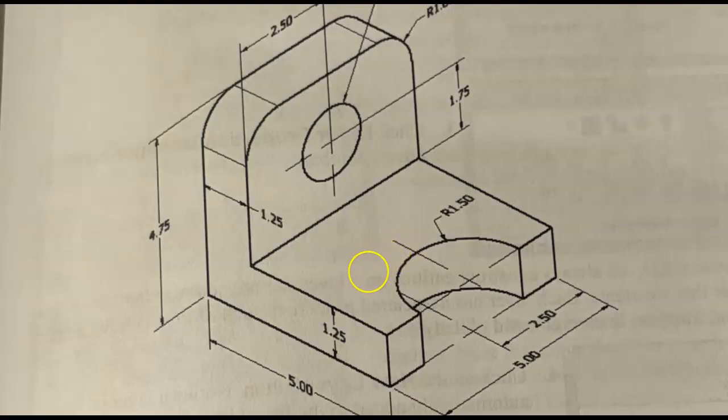Now do the same thing here. This is going to be 5 for the distance of the depth, tab 30 degrees. Notice it's putting it in the same place. So we can do that either way, and we can be in either of these, basically because of the way we're entering that command. All right, so let's go back to the ISO plane left.